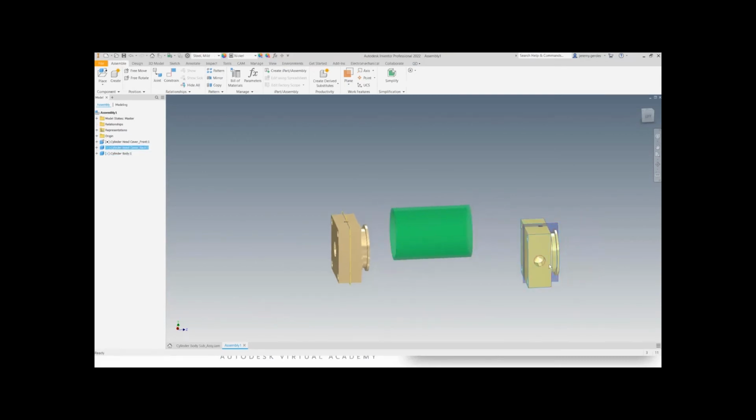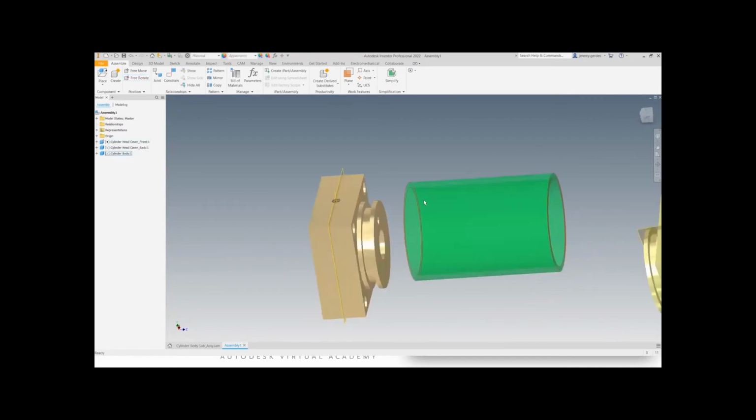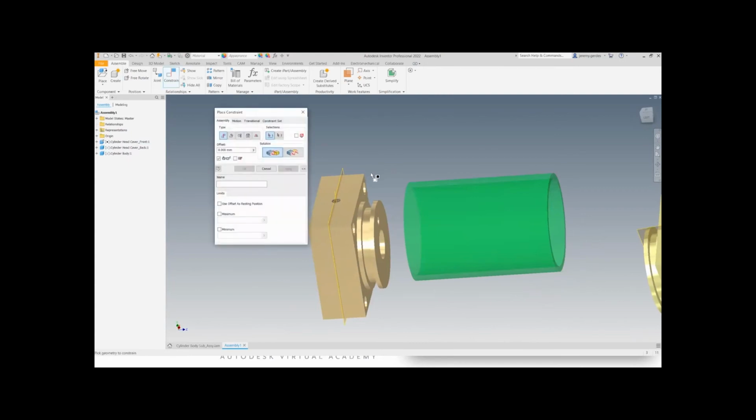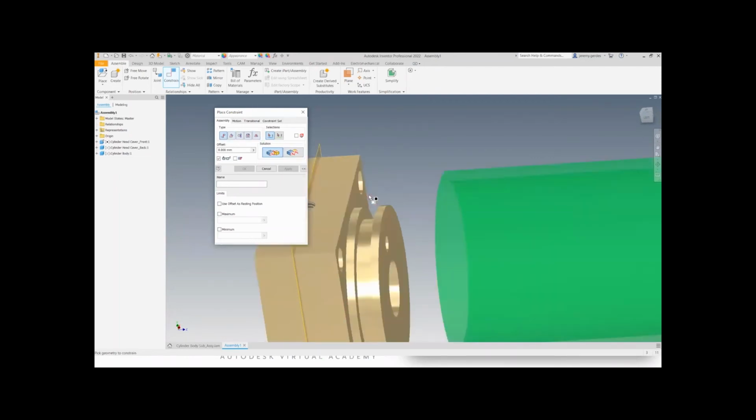But if you click on a part, hit G, you can rotate it instead of rotating the whole model. And so if I hit C, it's for constraint. And with the constraints, there's quite a few different options and tools to help you. You have a mate, which is the most basic, most commonly used constraint. And it'll let you constrain faces together, edges together.